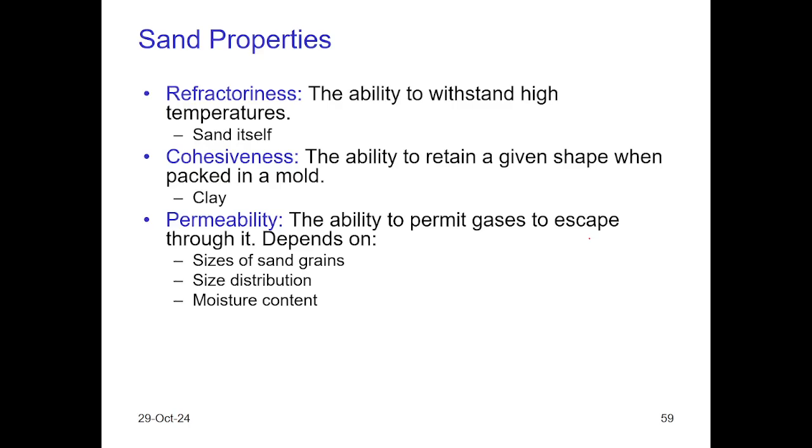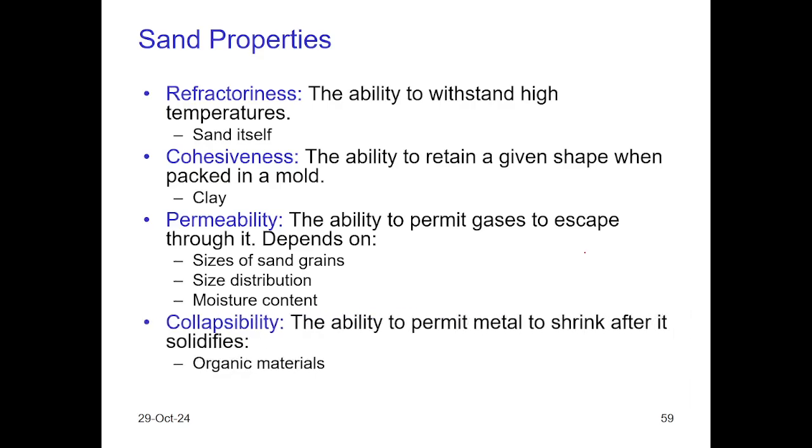Well, if the permeability of the mold is not in the correct order, then the only solution is a riser. Risers should be open to the outside while the molten metal is poured into the cavity, to allow the trapped air to leave the region. And collapsibility is the other characteristic, the ability to permit metal to shrink after it solidifies.